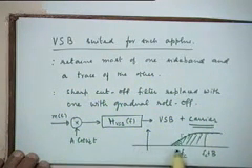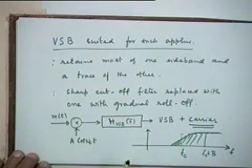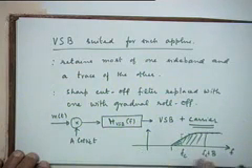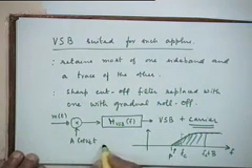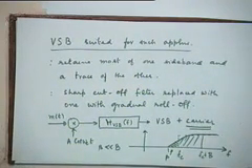Right? Of course, the similar thing will exist on the negative frequency axis. So your bandwidth will now be, suppose basically we are going down on this side by a small amount. Your bandwidth B may be large. For example, in the TV case it is 4 to 5 megahertz, 4.5 megahertz or something. There will be an overflow into the other direction by an amount, let us say beta, where beta will be typically much less than B. So you will be still saving a considerable amount of bandwidth, right?